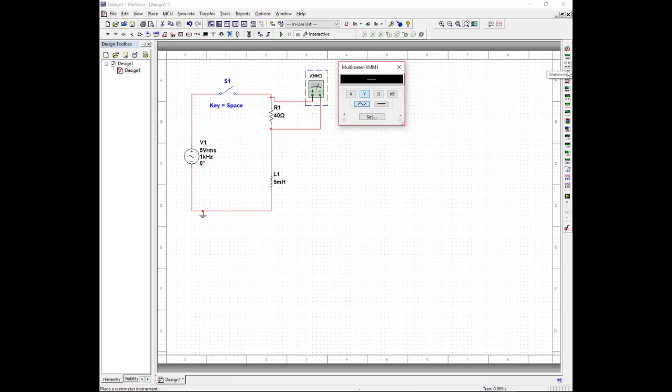So I'm going to go with the standard oscilloscope, the 2-channel one. We'll bring it down here, and again, just drop it where you want it. On our oscilloscope, the 2-channel one, you'll see that we have two channels, channel A and channel B, and in each channel we have two connections. We have the positive, which is our sensing probe, our measuring probe. Then we have a negative, and that in this case is going to be connected to ground. It will need to be connected to ground.